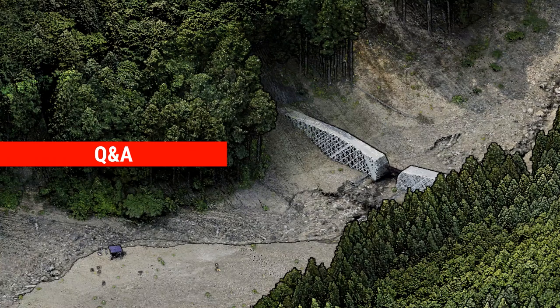So we have had customers, and it keeps happening that people come up with their own definitions or custom ground-to-grid scale factors or even local coordinate systems. The latter, which will be part of a future release, so that's in development right now. The local coordinate systems and determining transformations to match those. But yes, ground-to-grid scale factors are supported.